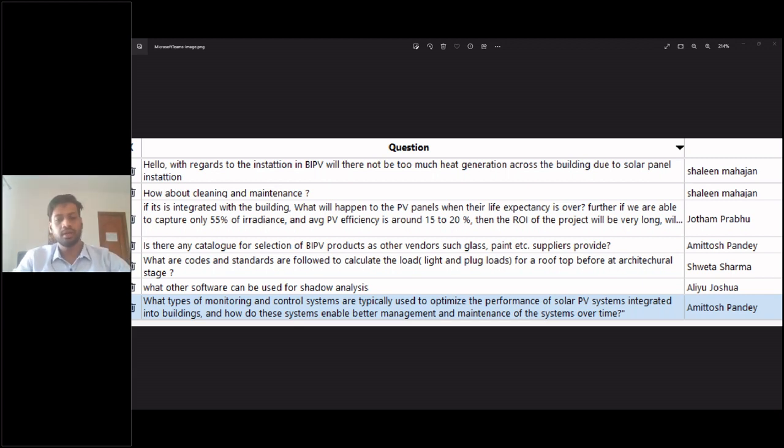That is basically your government supply, your BESCOM or ESCOM distribution boards. So we have control systems in place which will prevent this. We have mechanisms built into the inverters which will have surge protection, islanding protection, and all, which abide by all the IS standards prescribed for a BIPV as well as solar system.